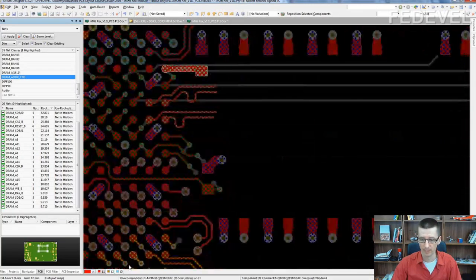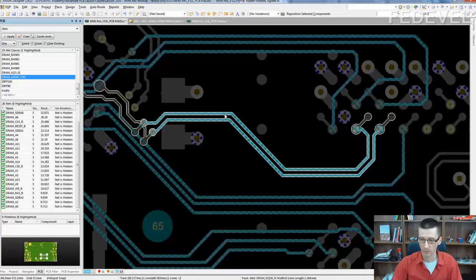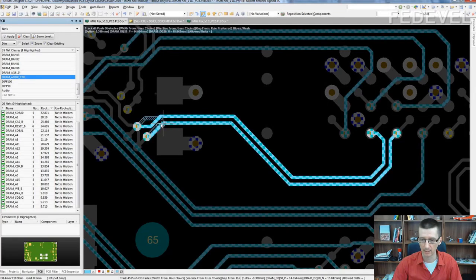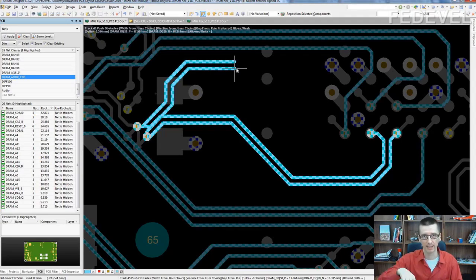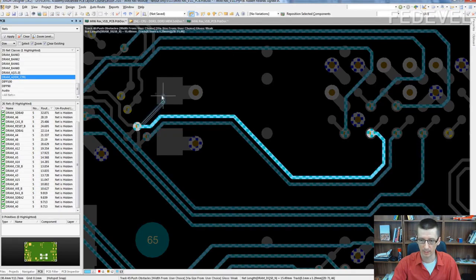And when we are speaking about differential pairs, usually you route differential pairs through this button. So both signals are routed together. Sometimes you may want to route one signal first and then the second signal. I'll show you. This way.